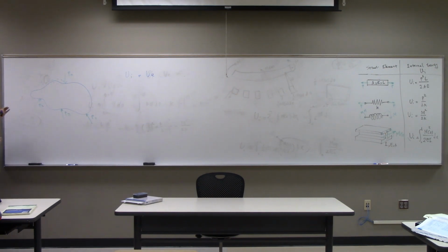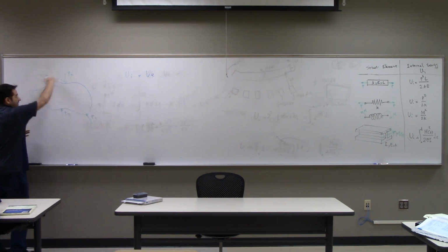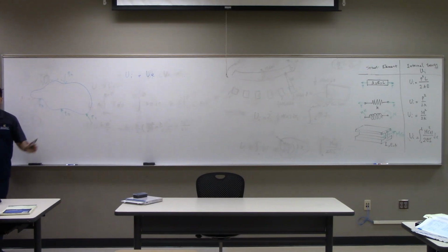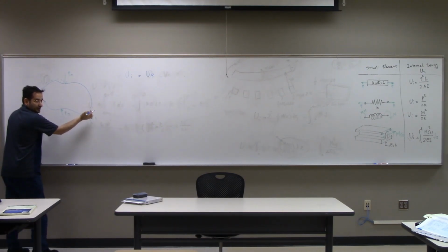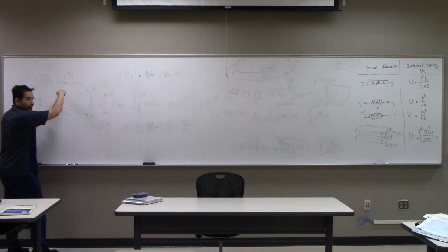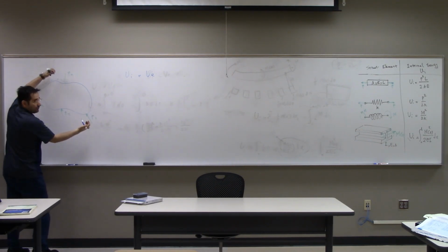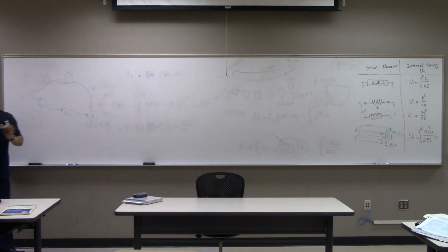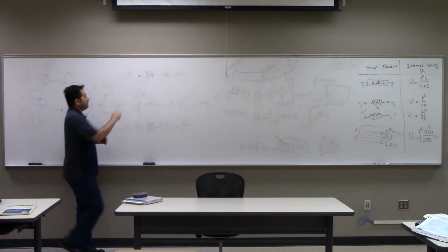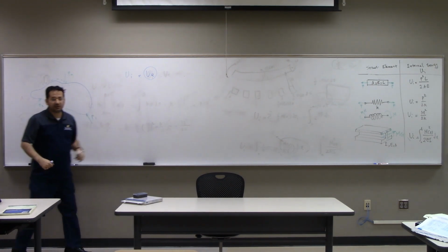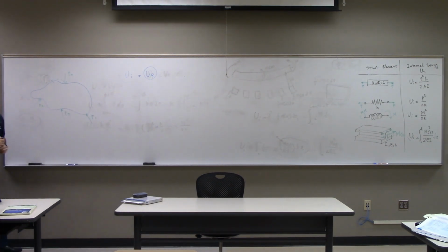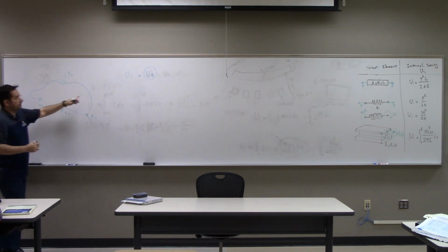So that means initially you don't have any of these loads. So this object is at rest. Then you add a little bit P1. In order to move, because this is sort of moving, then you have to constrain it, have some opposite direction somewhere in order to keep it in equilibrium. Then you add a little bit P2, P3, Pn. Then the work that you spend to keep it in equilibrium is equal to the energy stored in this spring, right? So originally you have this.